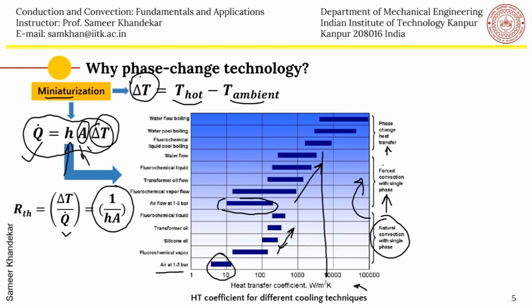Essentially, phase change occurs at isothermal conditions. The pressure and temperatures are locked, and therefore, if you remember your pressure enthalpy diagram, you go from the liquid phase to vapor at the constant temperature line. This is the constant temperature line.